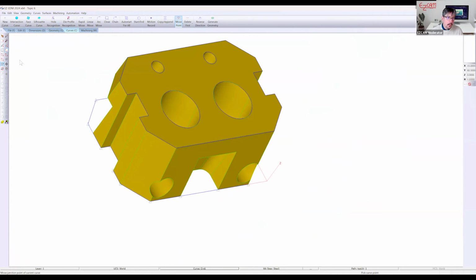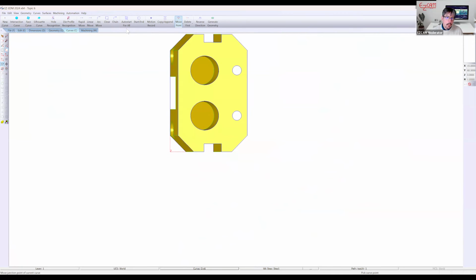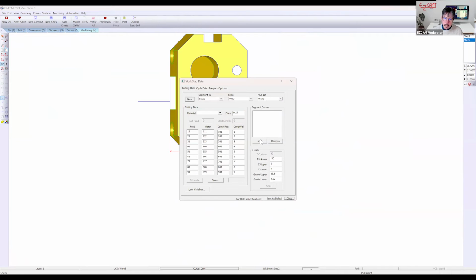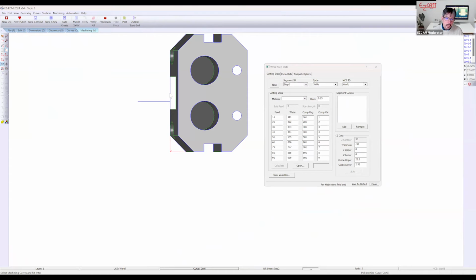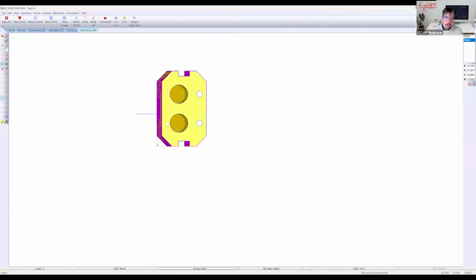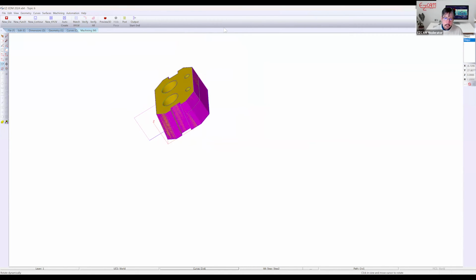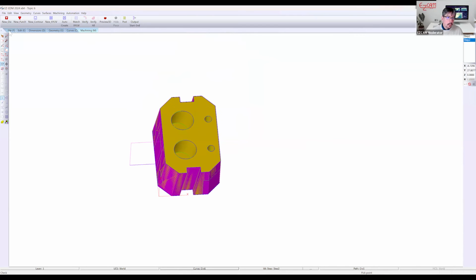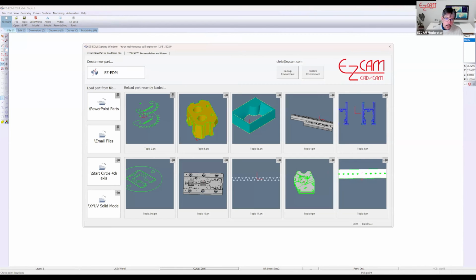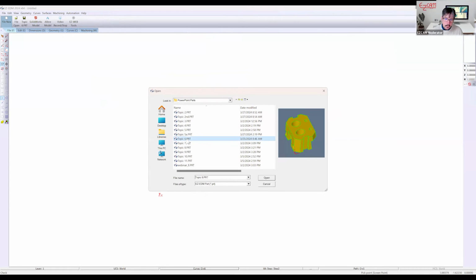All right, and we're going to build a start and end. Still XYUV. Let's pick the curves. Let's go to machining, select curves, bottom, top. And it's matched up. Let's see what we have for the next example.